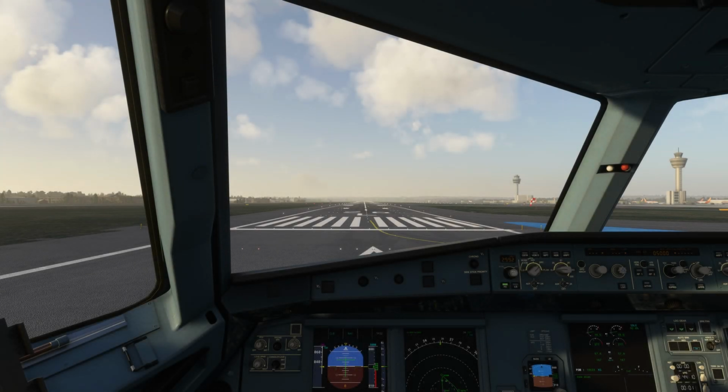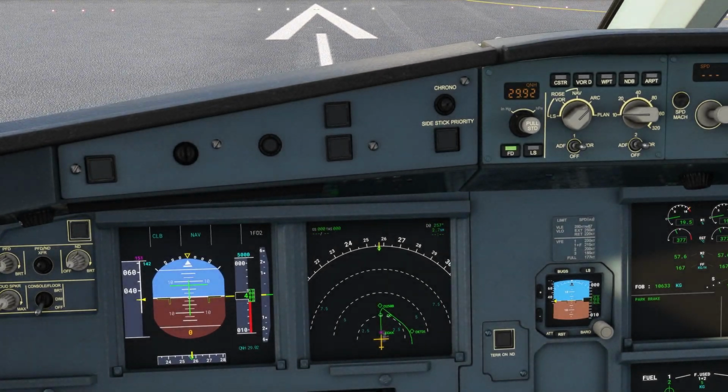Welcome to the Airbus 320 cockpit, and we can see there on our secondary display our flight plan. And we'll be having a look at that in a little bit more detail just now. What I want to do is turn your attention to this switch here. This is where we set our barometric pressure, and by doing so we'll set the correct altitude for the airport. Note as I turn the dial, the elevation or altitude on the primary display is changing.